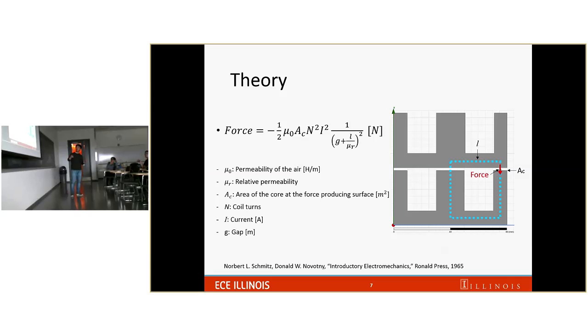What makes it move left or right in this system is the electromechanical force that is induced by the current here. N is the number of turns, which is fixed. The only controllable parameter is the current. There is another parameter that makes the force different, which is the gap difference, because the gap changes as I move. So to get the same force, if the gap is increased, I should put a larger amount of current to get the same force.